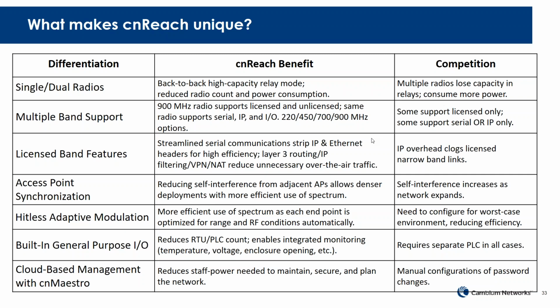And then latency, what are the latency expectations? Latency on this can be on the order of below 100 milliseconds. Of course, it depends on the payload size of that packet. When you talk about narrowband 12.5 kilohertz channels, as you adjust the payload, transfer time starts to have a larger impact on the latency. So the latency value will change a bit with payload, but you can kind of look at that 100 millisecond range as the target.